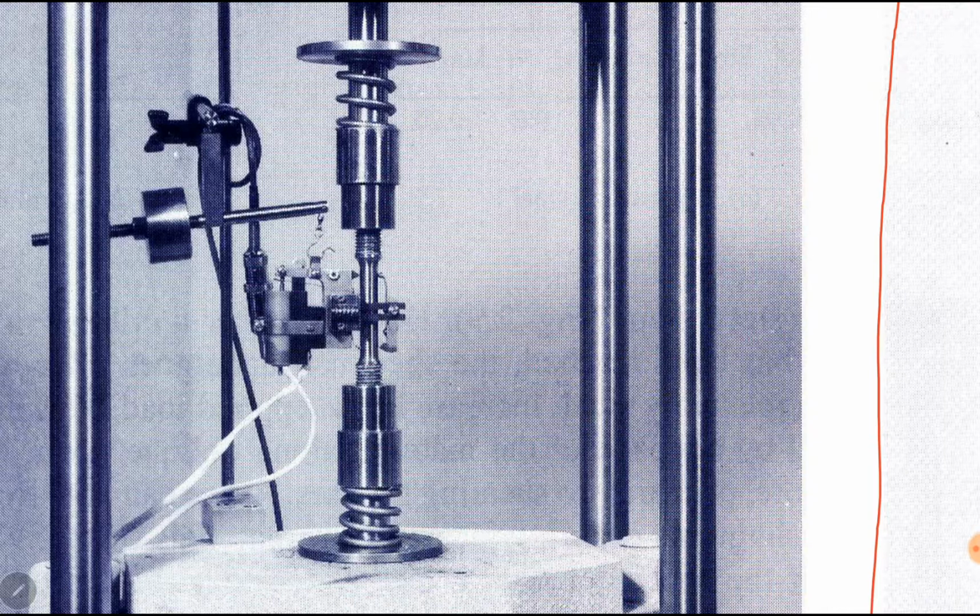So here somewhere near point B, there will be a value of stress below which the material will exhibit elasticity, and the point beyond which the material does not exhibit elasticity or elastic properties is called elastic limit. So when the strain does not return to 0 after the stress is removed, the material is said to behave plastic. Somewhere in the plastic region beyond point B, for example at point C, if we unload the material, it will return to another point, point D. At point D, strain is not equal to 0.